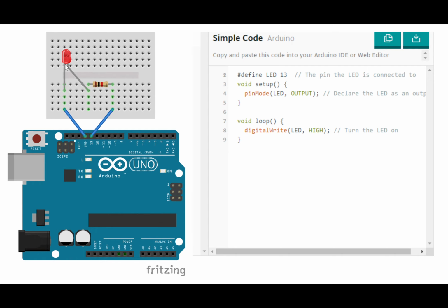One of the legs of the LED is going to be longer. That's the positive leg. You don't need to exactly remember it, but the electricity is flowing from pin 13 through the resistor, then in through the LED, lighting it up, coming out the other side, and going to ground, right? There is a complete loop here, and it has resistance. Great. We love both those things.